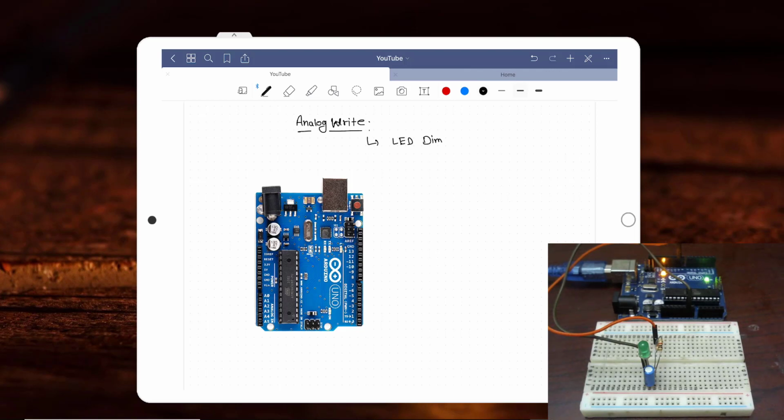We will be connecting our LED at pin number 9 with a resistor, let's say R. And then we will be connecting our LED at this resistor, and then it will be the ground there. As well as we will also be connecting a capacitor here, plus and minus. So once we generate a pulse width modulated wave like this,